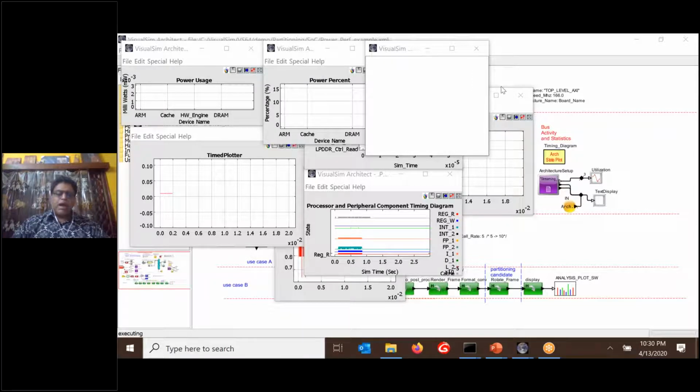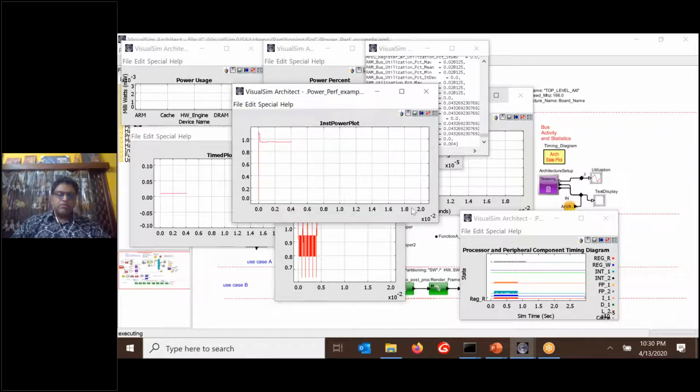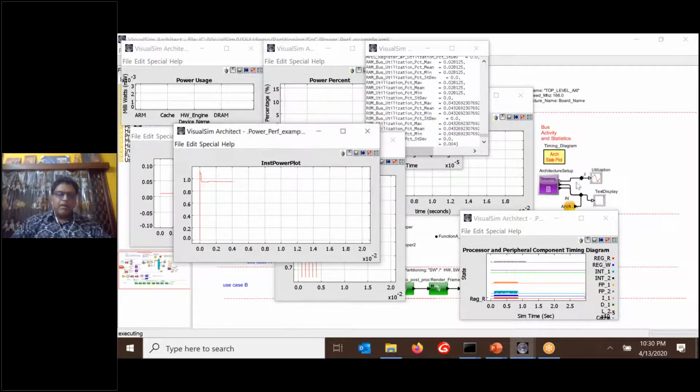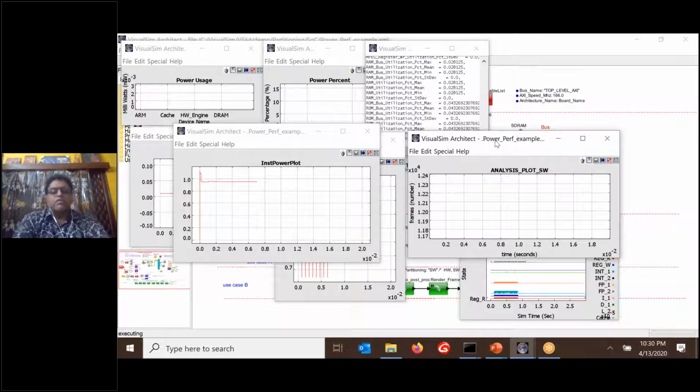So there are 2 aspects that I'm really interested in. The first one is this here on the power, and the second one here is the number of frames that I can process through this particular system on my display. So here you notice the power is pretty much, except for the small spike at startup, below 1 watt.